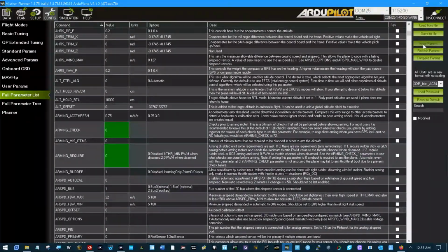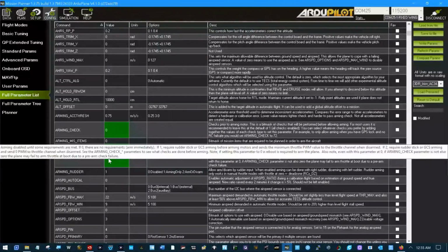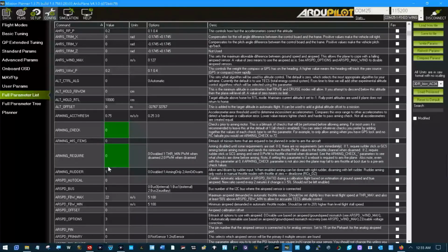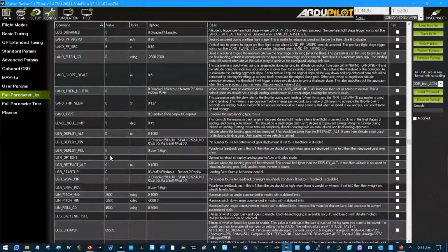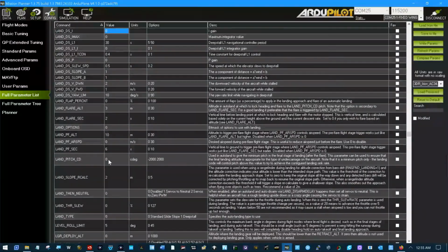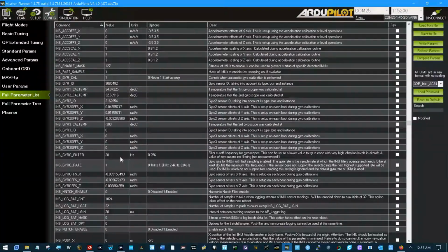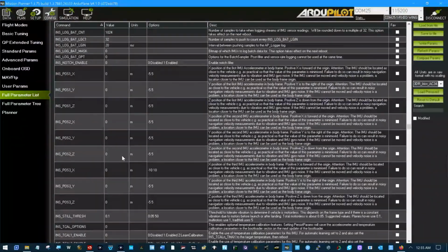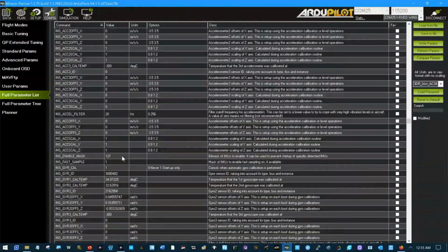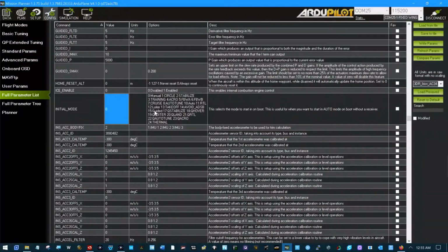You have to write them out to the platform. There's no arming checks. I've made sure both places here just to be for sure. It only needs one of them. I think this one. I do both of them. So the flight controller is going to come up immediately armed without anything else, and it's also going to come up in manual mode.